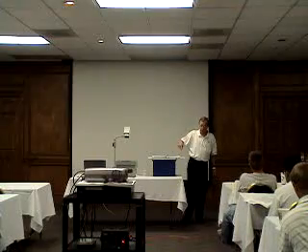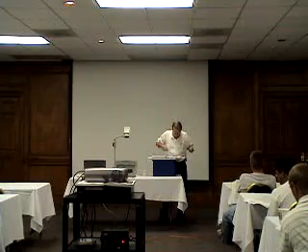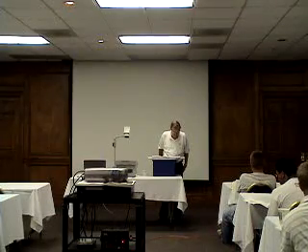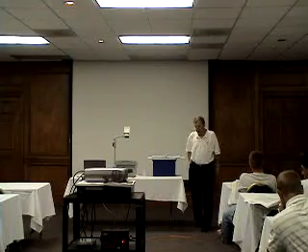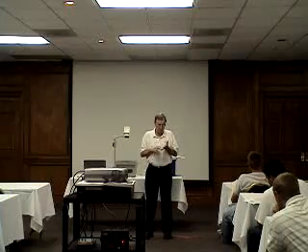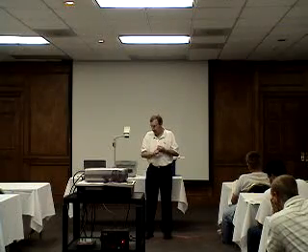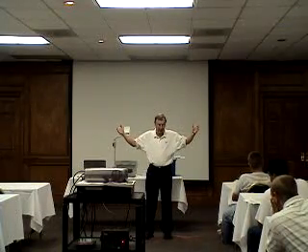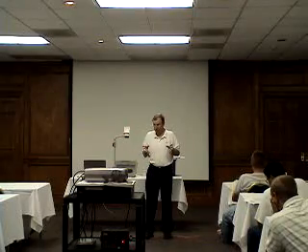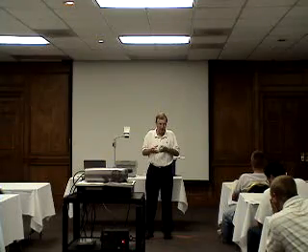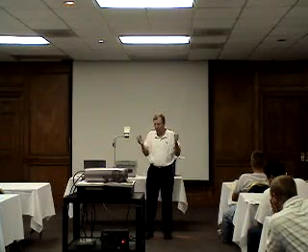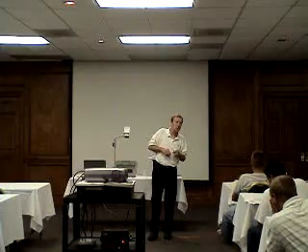We decided we'd start over on the upper left and work down. We always start with 0.245. That's our first number there. For our first increment of a mix design at the beginning of the year, you multiply the random number times the increment, which is 750 in our case, and wherever that result is, that's where the samples will be taken. In this case, it's 184 tons. We just figured to the nearest whole ton.